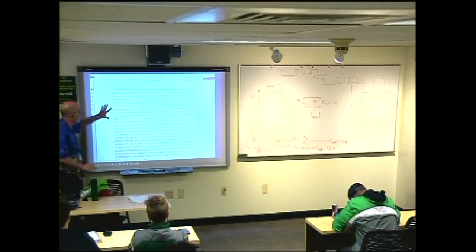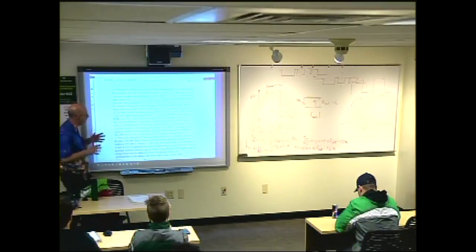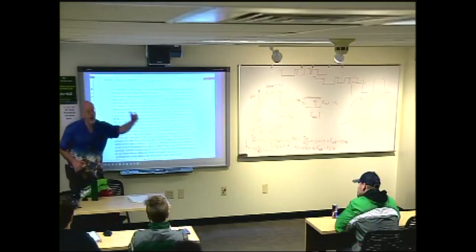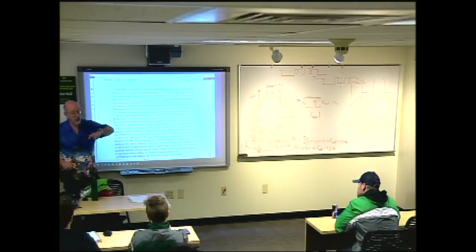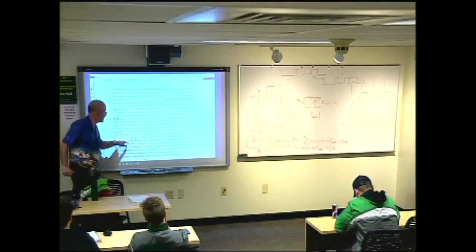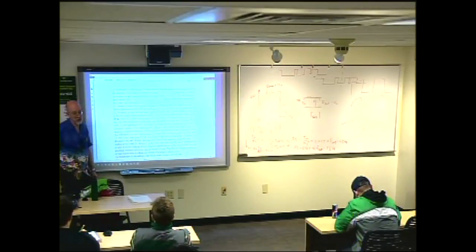So I've generated the 3-level by adding those two together. And then there's some stuff here about scaling the size of the flicker noise. It gets a little dicey as to whether we scale it before we put it through our filters or after we put it through our filters. So in particular for this flicker noise, I want you to scale it before you stick it through the filters. Okay?